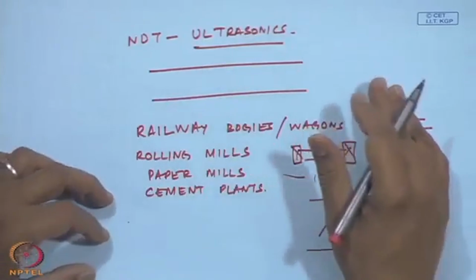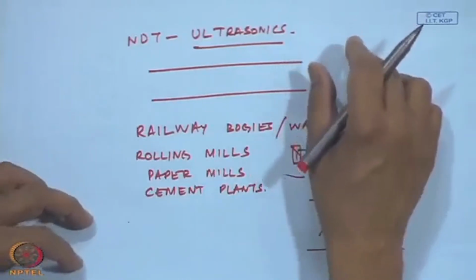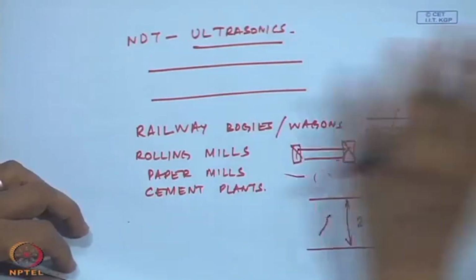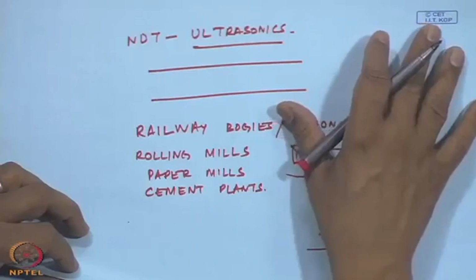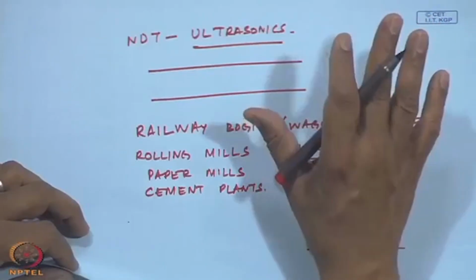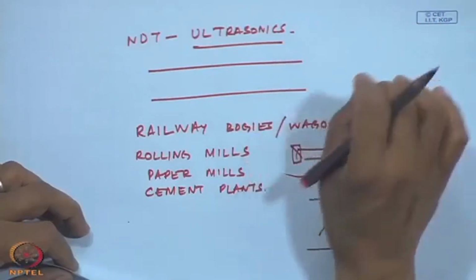Okay, we will discuss the dye penetrant and the ultrasonics in a later class, but in this class I wanted to focus on the dynamics of cracks in a shaft and how we monitor it. So, we know that we can measure the mechanical impedance of such a system, we can measure the natural frequencies of a system, because if cracks occur, the stiffness is going to change, and so the natural frequency is going to change, and then let us see how we can do that.